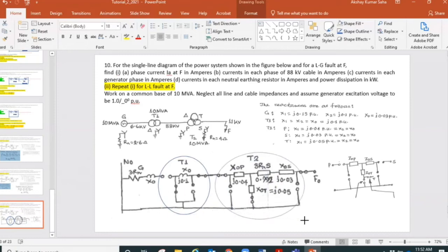So this is the 3-winding transformer. Look at the primary side, star connected grounded, so we close the series switch. We cannot do the parallel switch. Star grounded, this one is closed. Star grounded through a resistance, the resistance comes multiplied by 3.